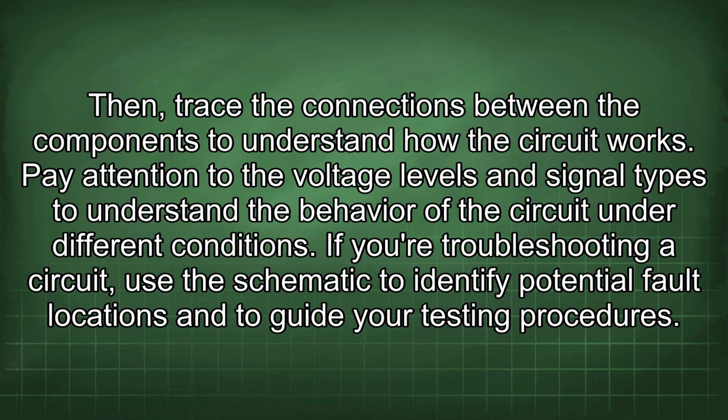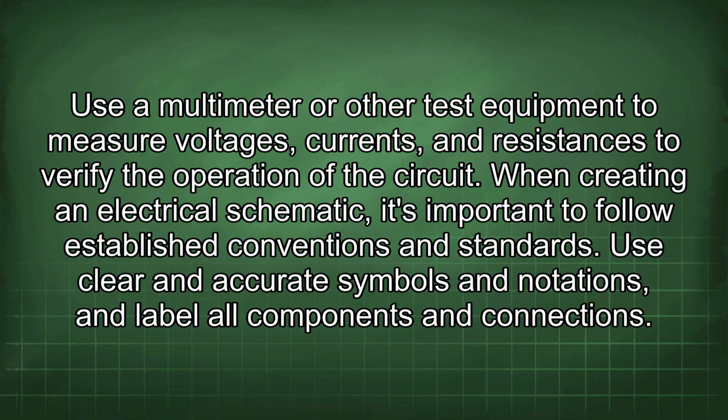If you're troubleshooting a circuit, use the schematic to identify potential fault locations and to guide your testing procedures. Use a multimeter or other test equipment to measure voltages, currents, and resistances to verify the operation of the circuit.